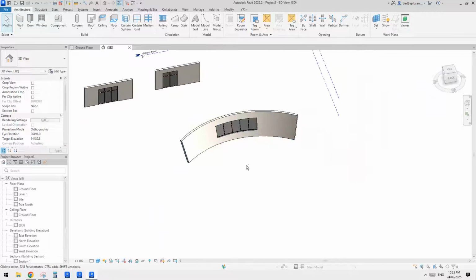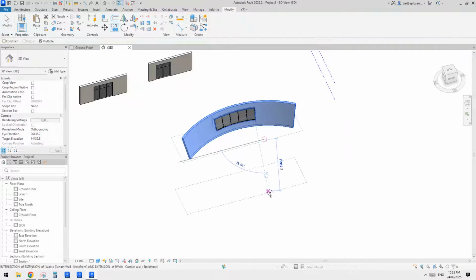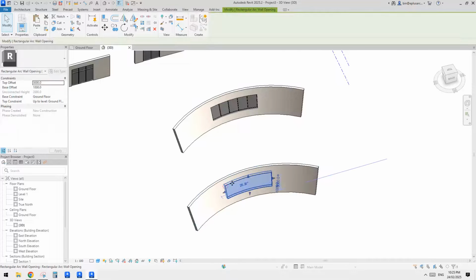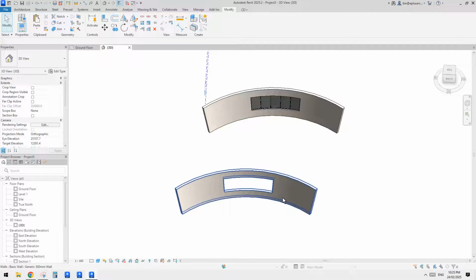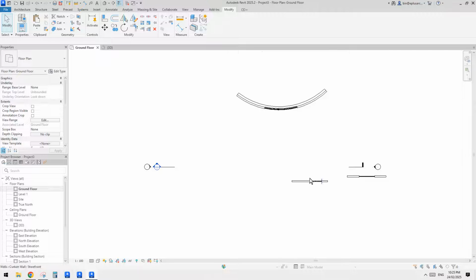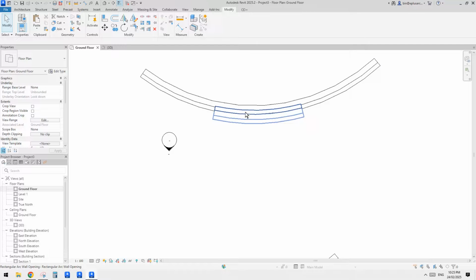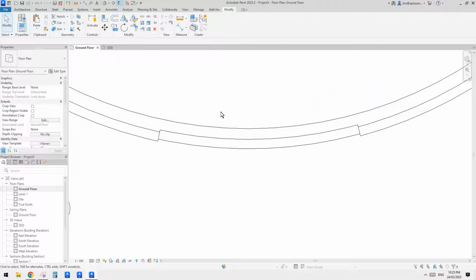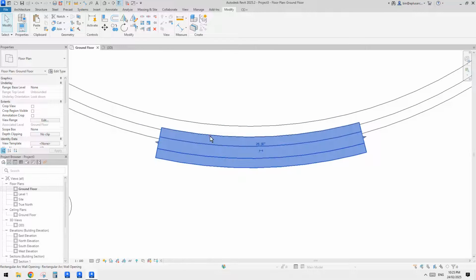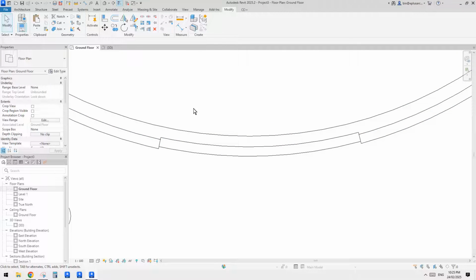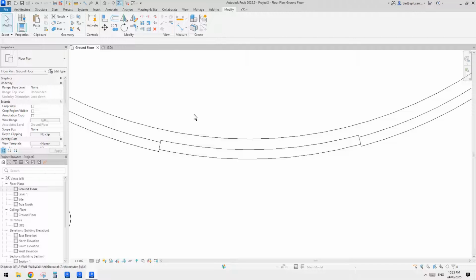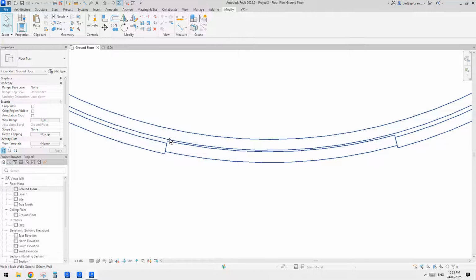So how about we try to create a wall? I'll just copy this one here first. And how can we create a window directly inside of this opening? I think we can also do that, but it can be a little bit tricky. So we know this window opening is from 1 meter to 3 meter. So I think what we can do is maybe just type WF, because we need to place onto the center line of the base of the wall.